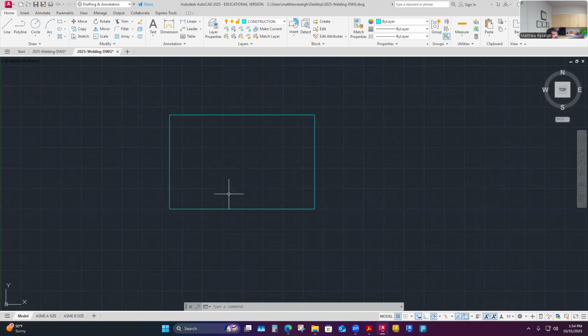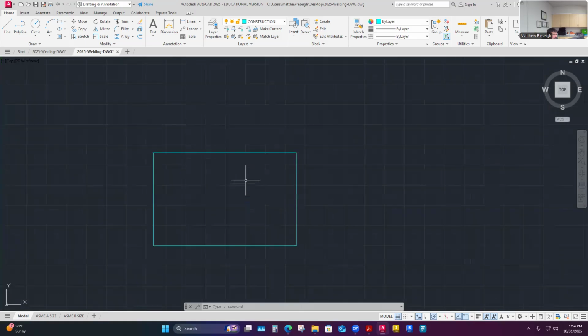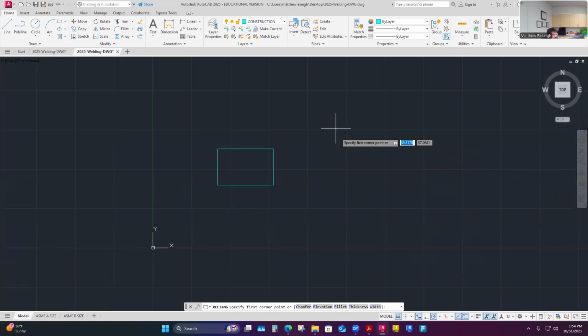So there's my rectangle. I just want to show you that's one way to do it, line by line. I could have set my boundary by rectangle. It's a draw command we have. We can draw polygons of different sizes and sides, and rectangles. If I would have just chosen rectangle, it functions the same. I could have picked anywhere in space to left click, and you click once, and then you start pulling away, and it starts building the rectangle. And then what you get is two dialog boxes. Like most geometry has two dialog boxes. Even a line has an X and a Y dialog box, essentially.